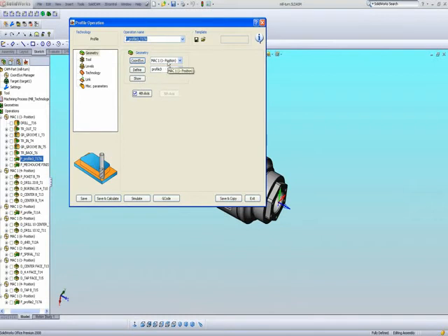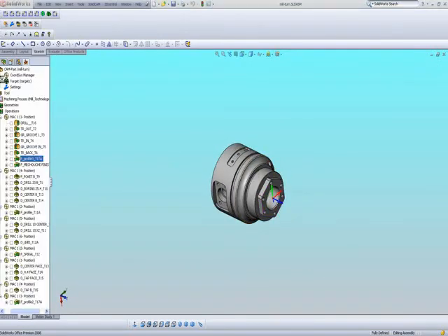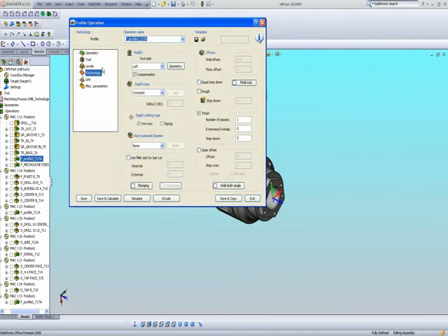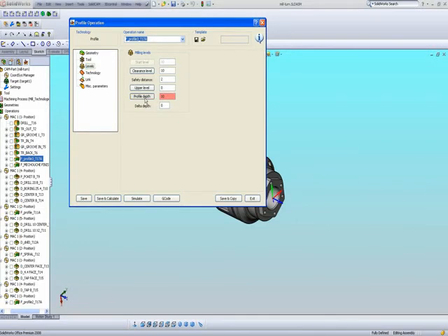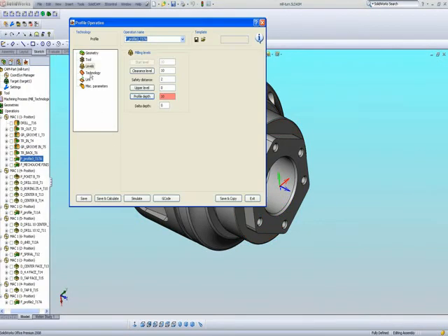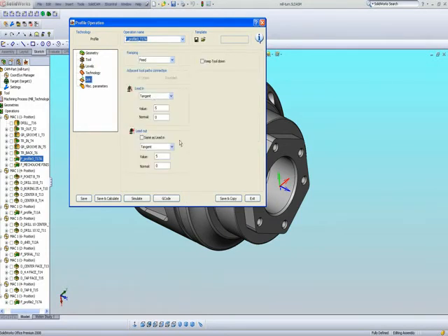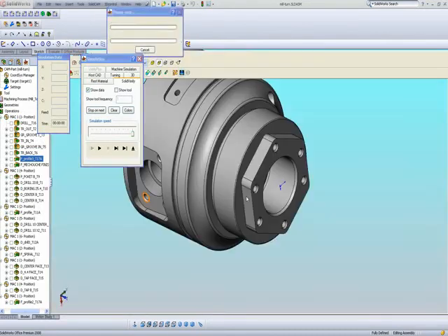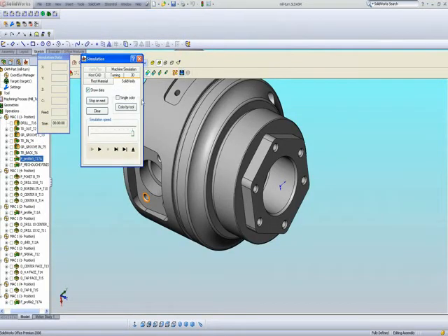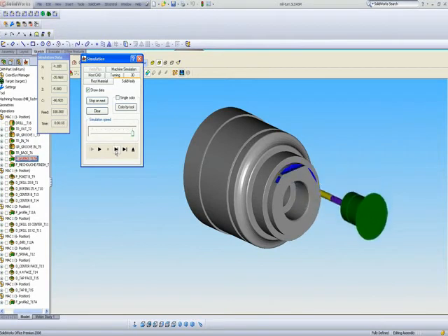where I have, as I showed you, my Mac 1 position 1, my geometry, my technology, my upper levels, my profile depth, as shown here, my regular milling technology, my links, approach as a tangent, lead out also as a tangent, and if I were to do my simulation using your solid verify, you'll see that my tool simply will go around this area and would simply mill out the entire area as seen over here.